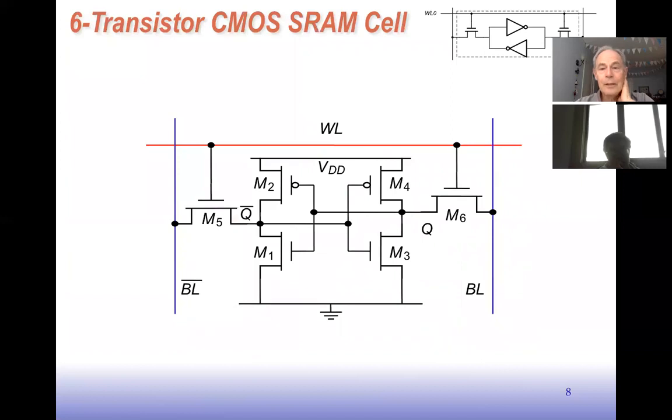So first SRAM. The bit cell that we use for SRAM, as I mentioned earlier, uses the property of cross-coupled inverters, where we can use the restoration property of the inverters to keep a very robust storage of a 1 or a 0. It'll store either a 1 on this side and 0 on that side, or a 0 on that side and a 1 on this side. So the value is actually held differentially. We have both versions, B and B bar, in the cell, which is nice, and we can use that to our advantage to make the circuit simpler.